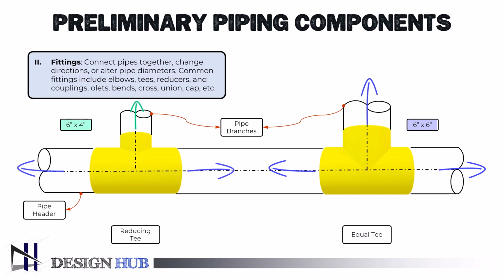A note defining the header size and branch size, 6x4, as illustrated, must be attached to a branch that is 6 inches or less. This is necessary since all pipe lines 6 inches and smaller are drawn as single lines, making it challenging to discern between pipe diameter sizes. Take note that installing the fitting within the header requires 3 welds to be made on the weld T. The weld dot on the 6 and smaller branch exit on the reducing T should catch your notice in particular.